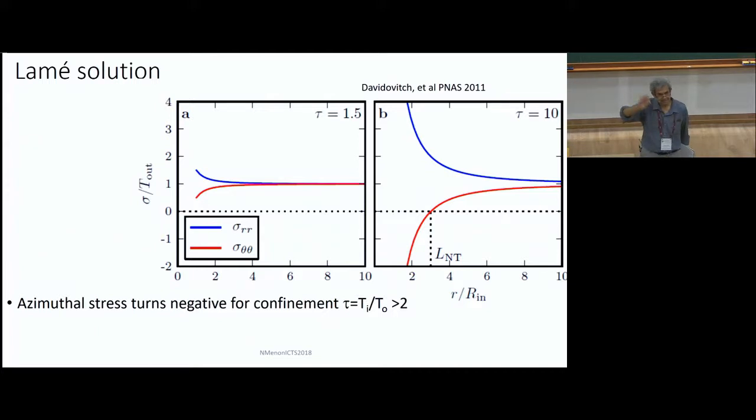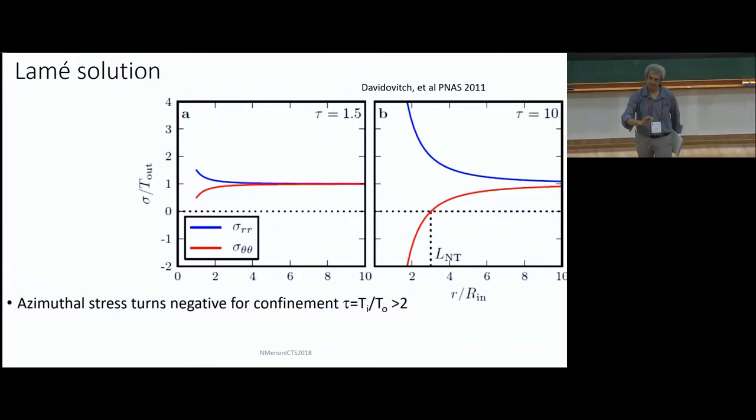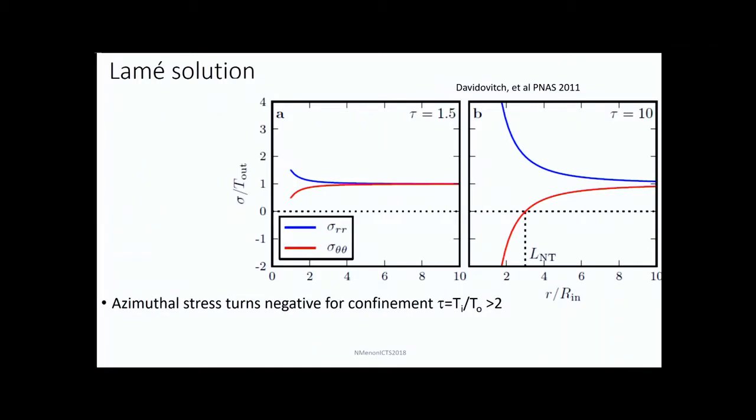So the right way to start with this is not to think of the planar state, but to think about a state that can wrinkle as much as it wants to take away all the extra material. Okay? And then you say in here, sigma theta theta equal to 0. It's done whatever it needs to do to take care of all the extra stresses. Everything that is being pushed on by its neighbors has decided to leave the plane and be happy. Okay? And in here you solve